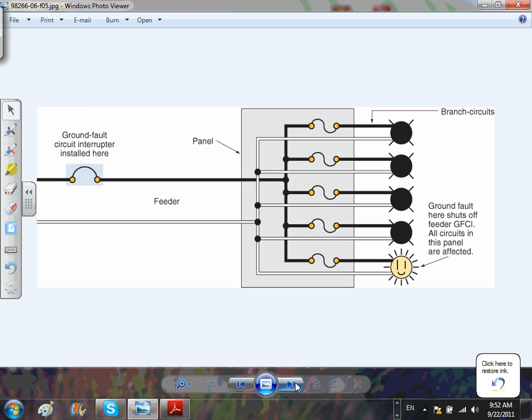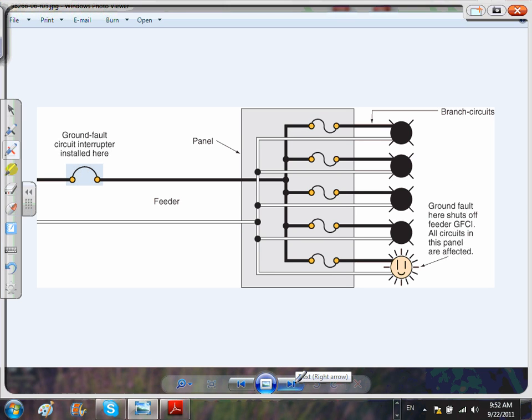Okay, so moving in here, we can have a ground fault. This is, as I said, more common overseas. I've seen it this way, where at the 100 amp level you have a ground earth leakage device. You have an earth leakage device mostly rated for 30 milliamps.